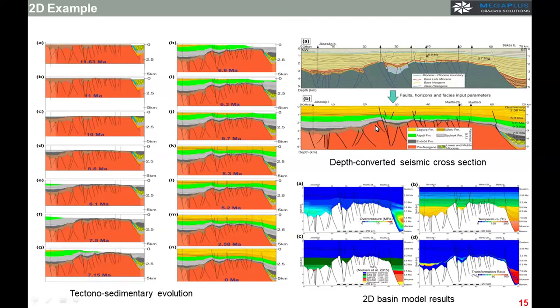Actually, you give the software the zero time, 0 million years, and after that you give it the time of every strata from your interpretation, and it starts from this current depth, calculating the compaction from the previous history inside the database of the software, and uses the depth you give it for the normal compaction trend at the time of 0 million years. It can build your model from 20 million years, for example, until the recent 0 million years when you reach the current time.